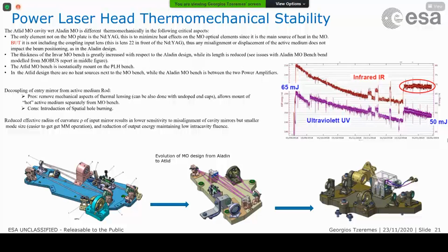Even for mobile systems, you buy a top-end air conditioning where you operate your LIDAR, you switch it on and you know that the temperature during your tests will vary by 1 or 2 Celsius maximum. So you're pretty well off. But when you're rotating around Earth, for example, you go from minus 35 to plus 55 in a few minutes period. So there's a constant thermal cycling of your instrument.